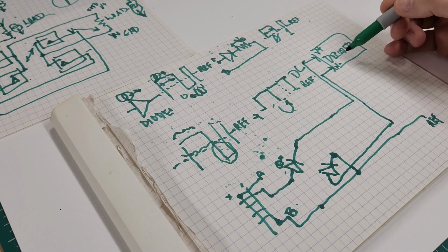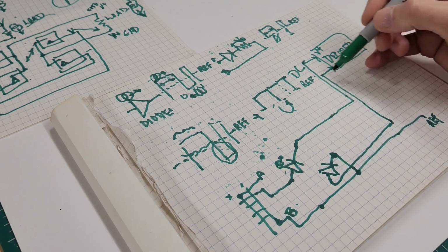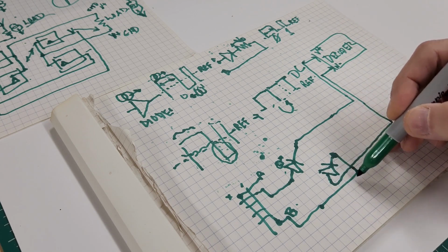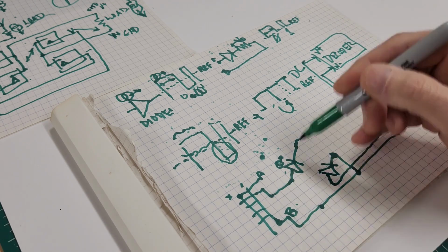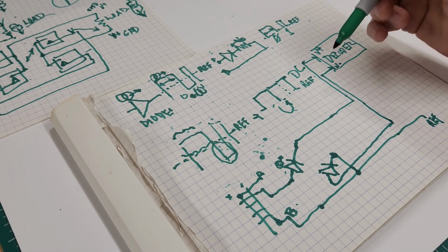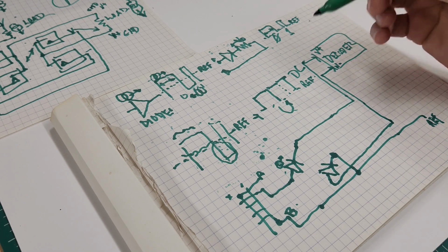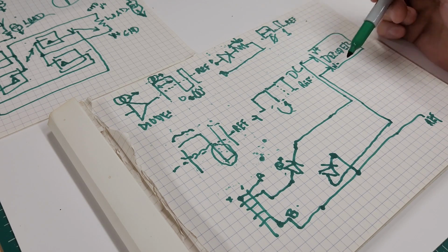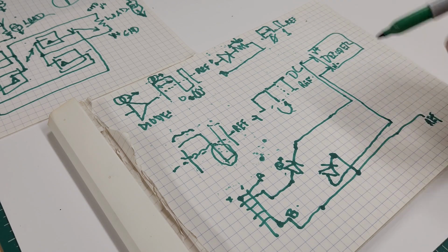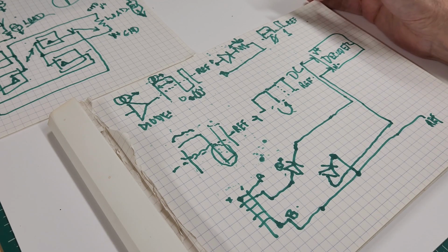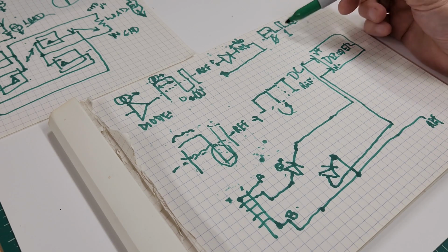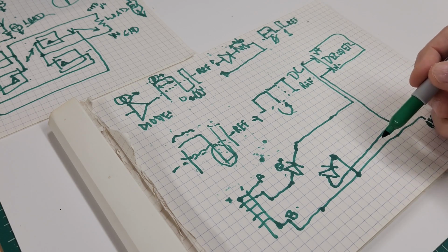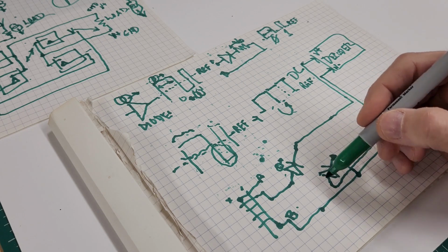But at any rate, you can see that if the current is flowing this way, when the current returns, it's got to go back through here and go back to B, from A to B. So that's how that would work if we were only going to be using a signal like this to power the decoder. But we don't want to do that. It's not a very healthy thing to be hitting a decoder with a chopped square wave. So we want to refine this a little bit.